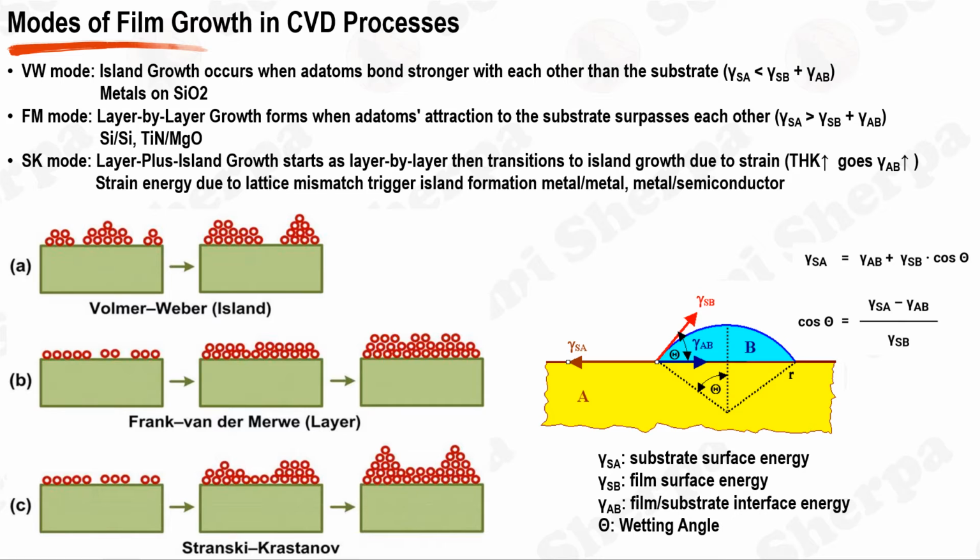This growth mode operates inversely to the first, occurring when the adatoms experience a stronger attraction to the substrate than to each other. Under these conditions, the adatoms scatter across the substrate, forming a thorough monolayer before commencing the construction of the subsequent layer. This results in smooth, high-quality films and is highly sought after for applications that necessitate a uniform and defect-free film. Achieving this growth mode, however, is notoriously challenging due to the precise control required over the deposition conditions. Lastly, the layer plus island or Stransky-Krastanov growth serves as a combination of the two preceding modes.